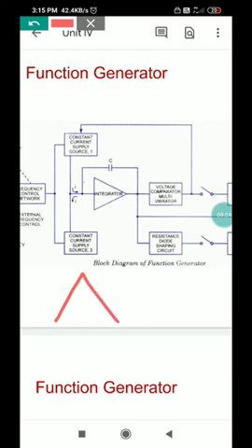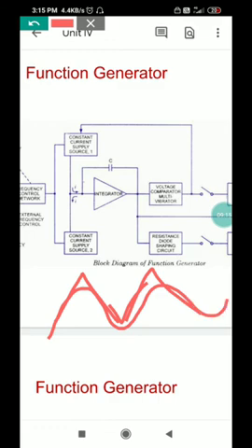You will get a triangular wave. This triangular wave is passed through a resistance shaping network, which will shape this waveform in a sine format. So triangular waveform will become a sine wave. We don't have to see much more detail about how this resistance diode shaping network works. So we just say that this particular network converts a triangular wave into a sine wave.